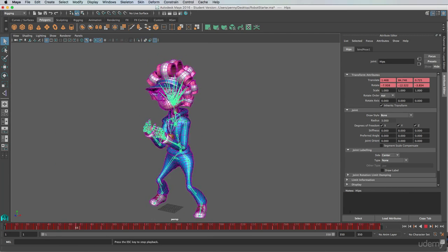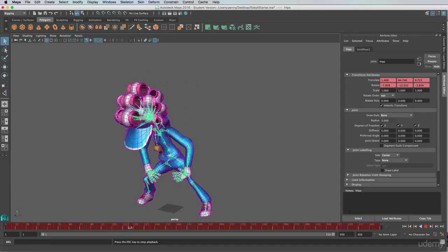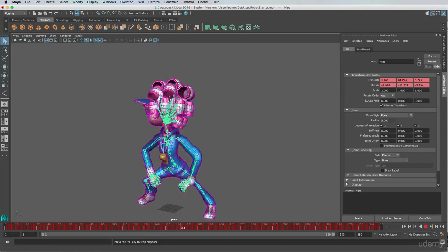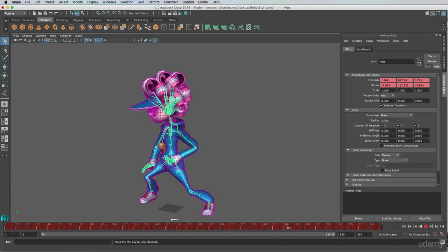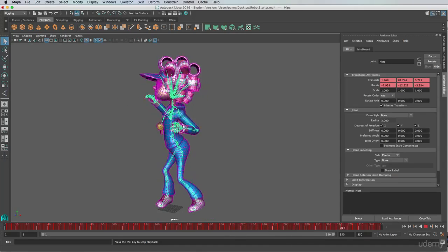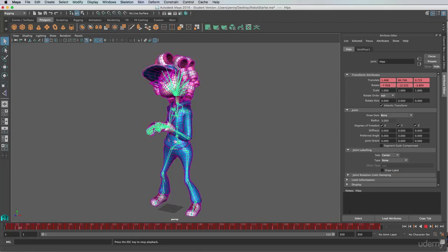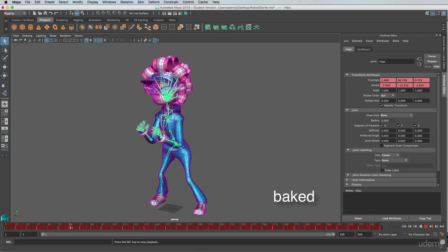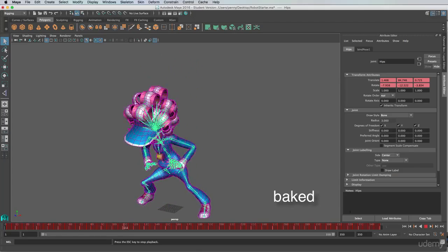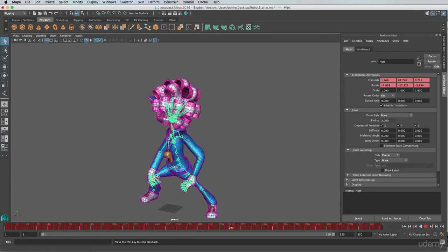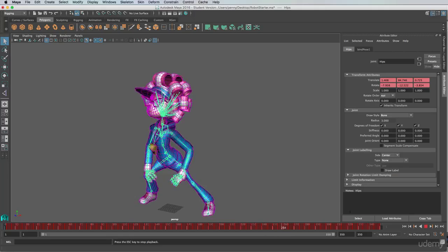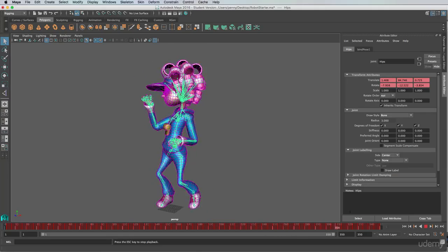Such complex animations are better made in 3D animation programs outside of Unity. When they're imported in, they're usually in a format called baked, which means that each keyframe is baked into position and retains all of the information. All of the tweening is removed so that there is a single keyframe at every frame in the animation.